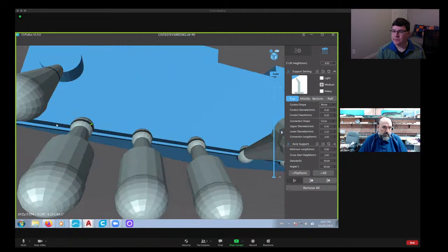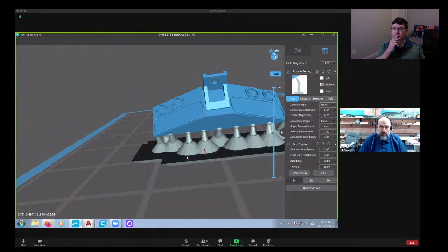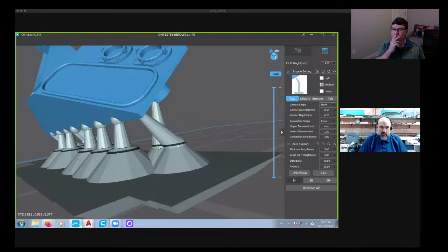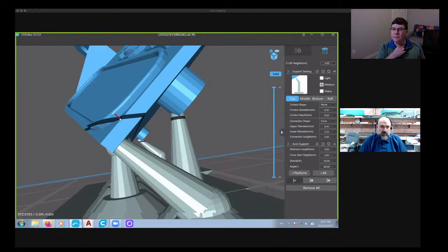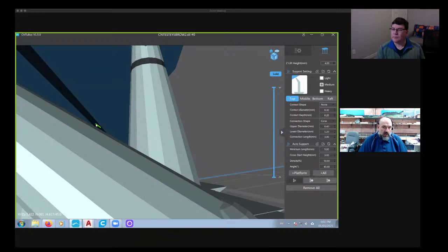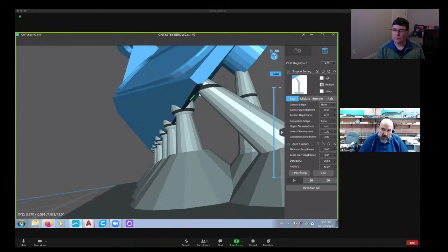Okay. Right, so go medium, medium. Now you can see on the corners, we've got support. However, yeah, this one's perfect. It's hard to get a really good angle, but there's no island here. This will print, the support will print before the part. And that's what you want.